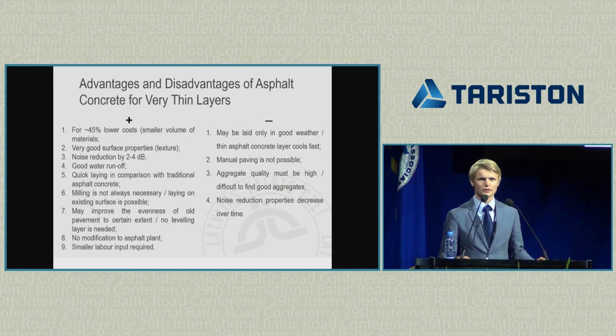And now more about thin overlays. Advantages: lower costs, good surface properties, noise reduction, good water runoff, quick laying, milling is not always necessary, may improve the evenness, no modification to asphalt plant, and of course smaller labor input required.